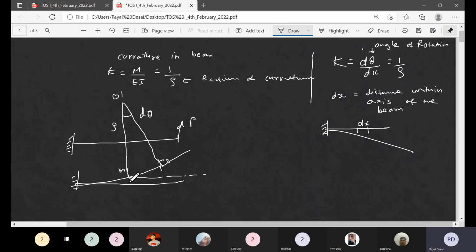from here to here, let's say point 1, when you travel forward, if my deflection is y, instead of y we can use the symbol v. So when you travel from here to here, let's say the deflection curve is at point 1, then here the deflection is v, and here the deflection will be slightly more. And how much is the increase? v plus dv, it will increase slightly, right. So when you travel from here to here, the deflection happens, and from this end to this end, over a smaller differential length, the increase in the deflection is dv.